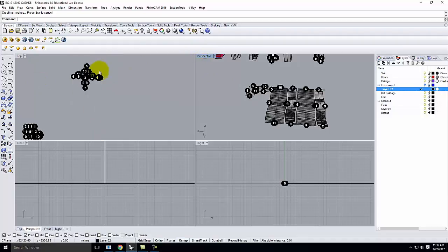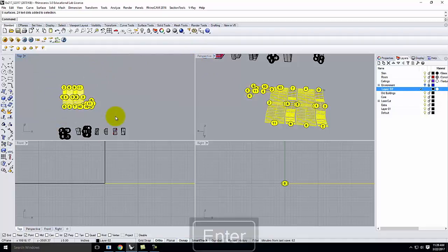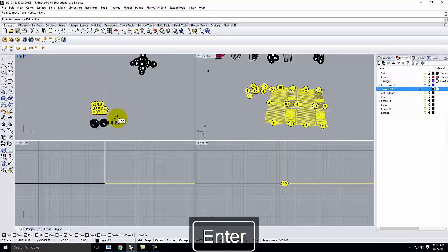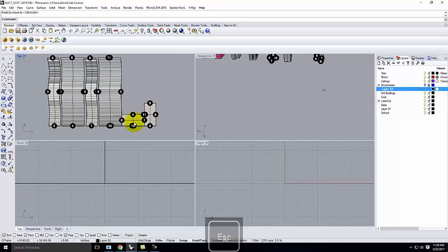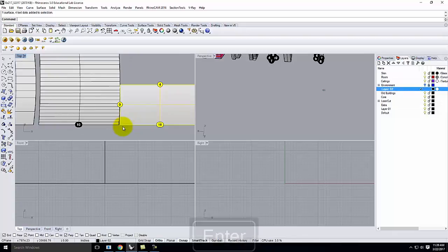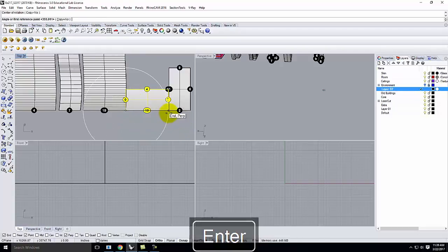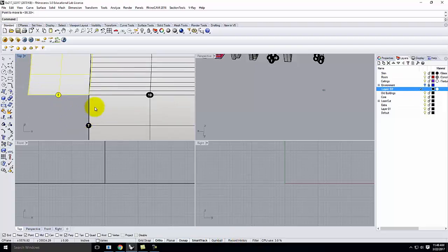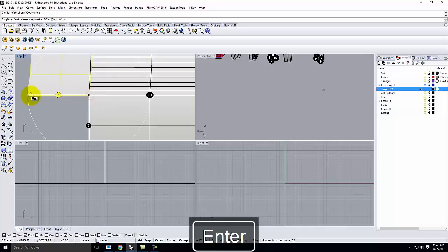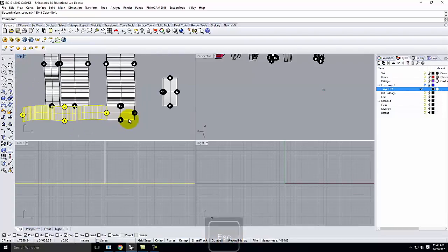So just like I did with this one, I'll take my parts. Let's move them up over here. There we go. And let's take that first one. Let's move 10. Rotate. Be there. 7. Rotate. Notice I'm not using rotate 3D, I'm just using regular rotate.